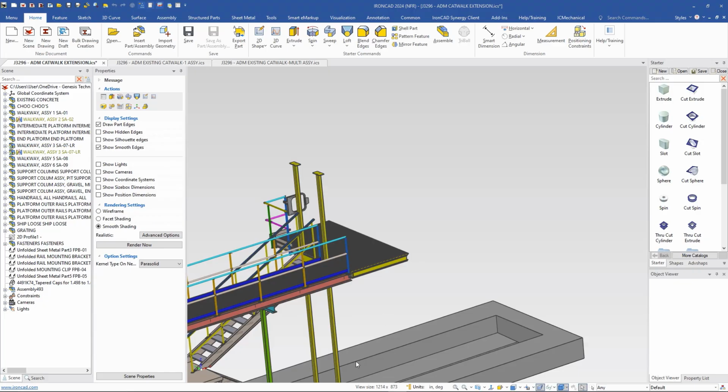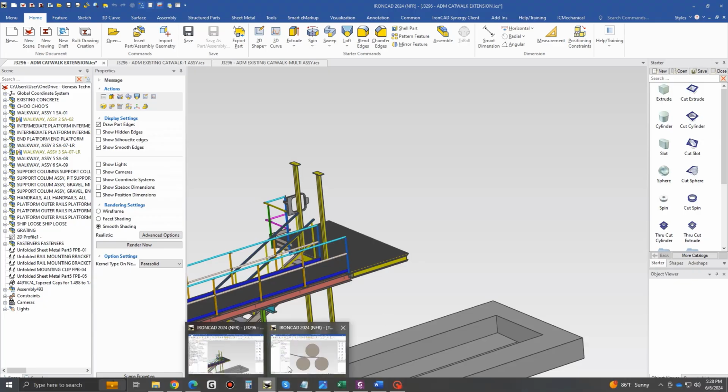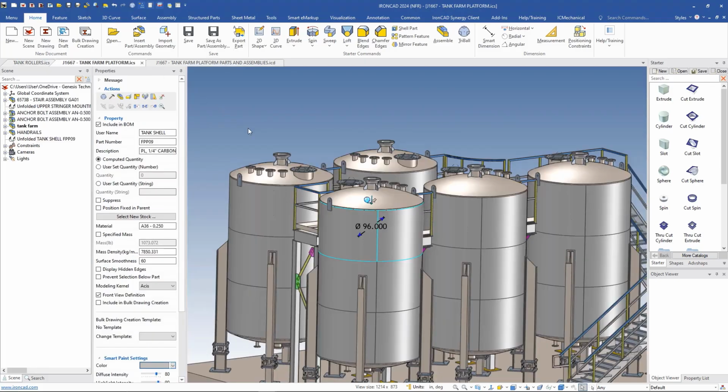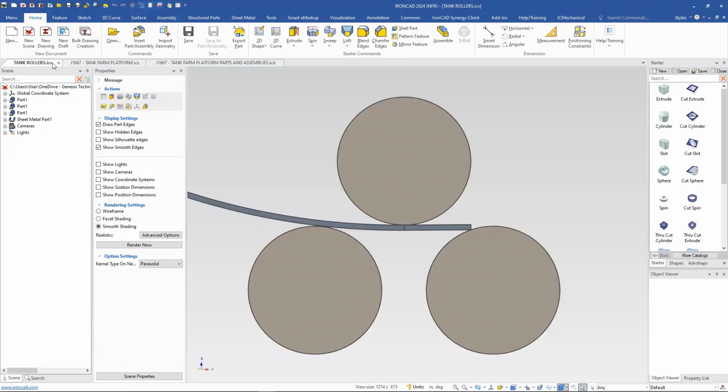What I would like to demonstrate now is a very useful tool for adding features to sheet metal flat patterns. This can be very helpful as an example when rolling sheet metal. Oftentimes, fabricators will want to add extra stock and trim the excess so that they get a truly round part. This comes in handy because during the rolling process, there is always a flat spot at the two ends due to the orientation of the rolls.